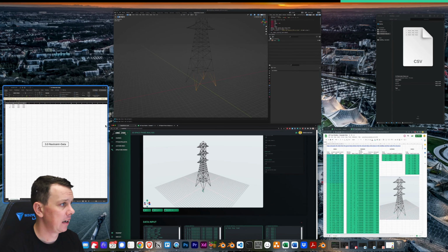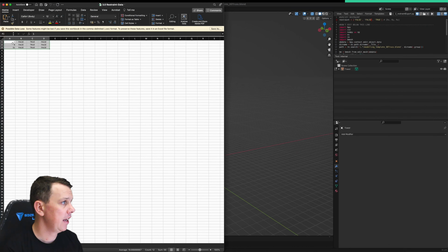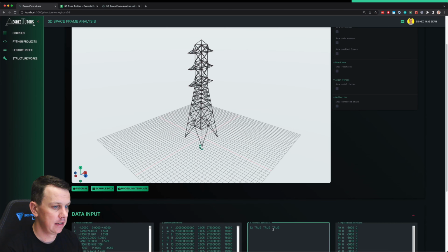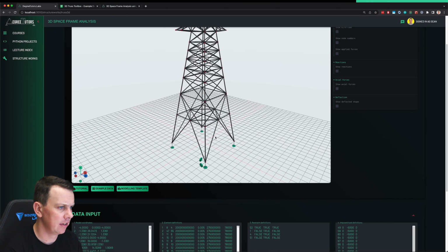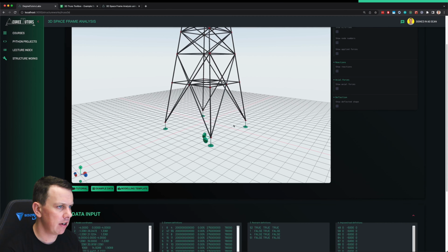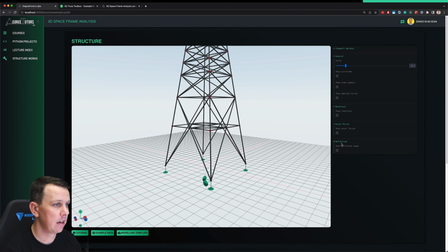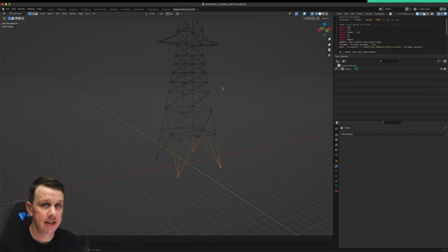But what it means is you'll notice that here that was false, false, true, but what got exported is false, true, false, because that's what we're going to bring over into our solver, right? So let's just take that, drop that in there, and you can see now our restraint model is different. We have just vertical restraint on these nodes and a full pin on that node, and in that case you run it again and generate a whole new set of results. Okay, we won't bother doing that just now. So that's how you deal with different types of restraint in the same model. You just do multiple exports and combine the data from each.